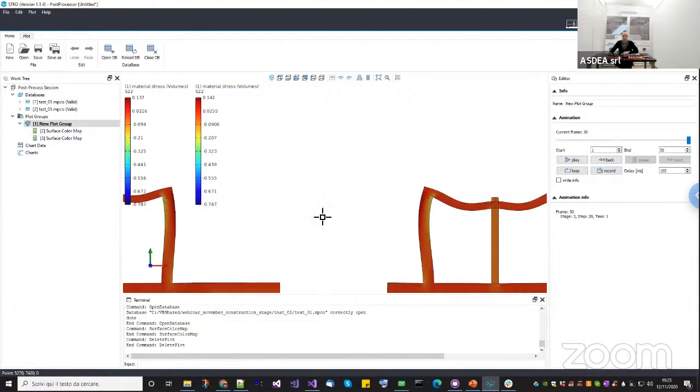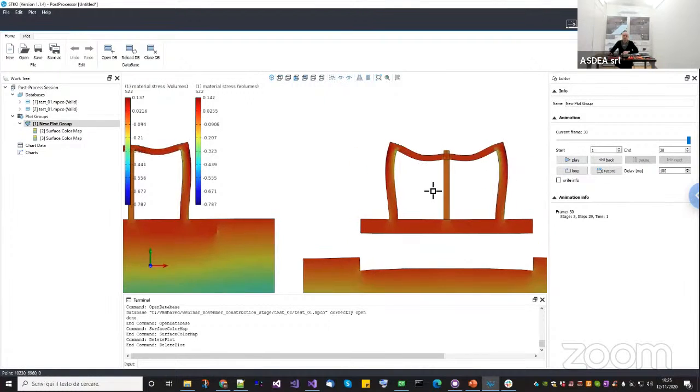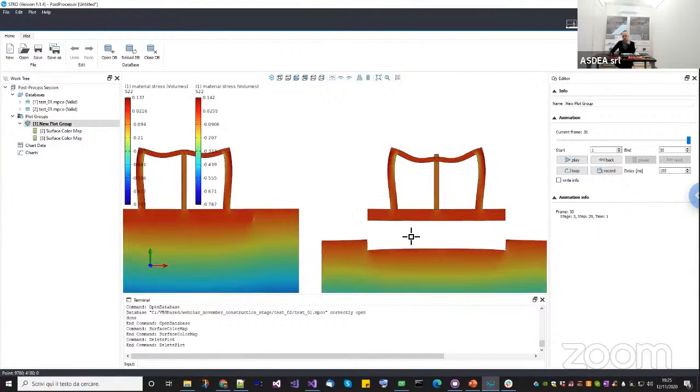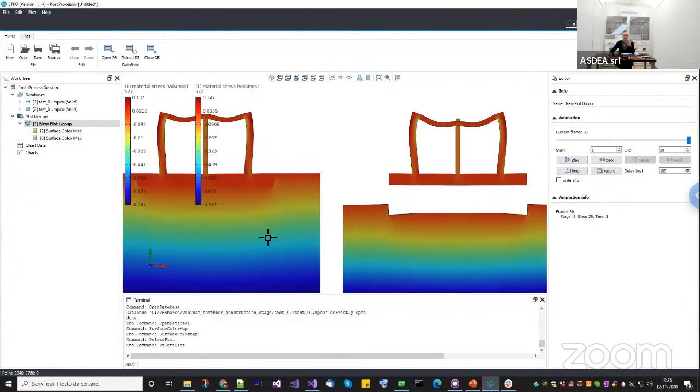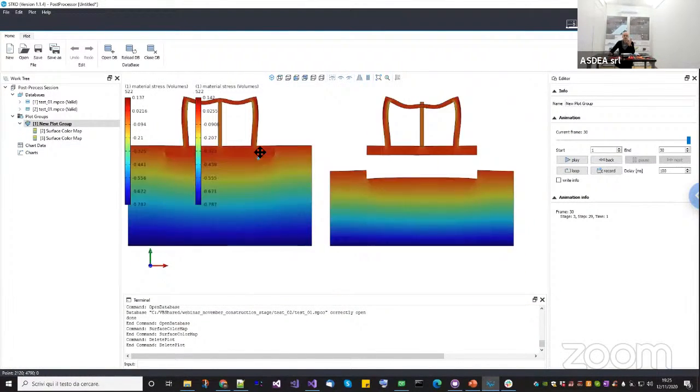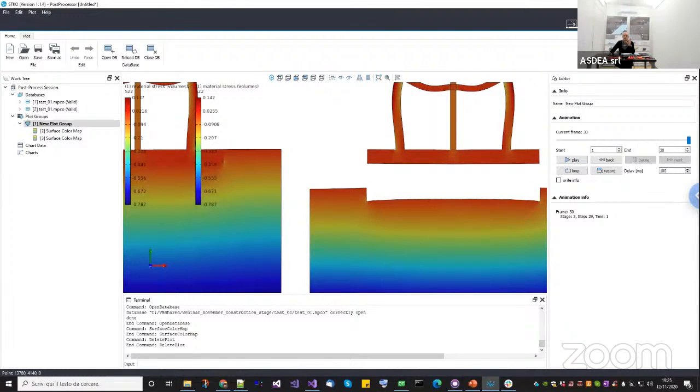The only difference is that this one is attaching through the kinematic constraint the displacement of the new model to the previous one only in terms of the delta displacement. So it is exactly the same model. As you can see, the stress state is the same here. There is no problem, and it is just more efficient.